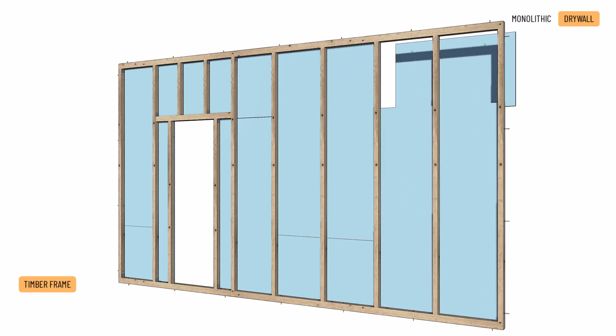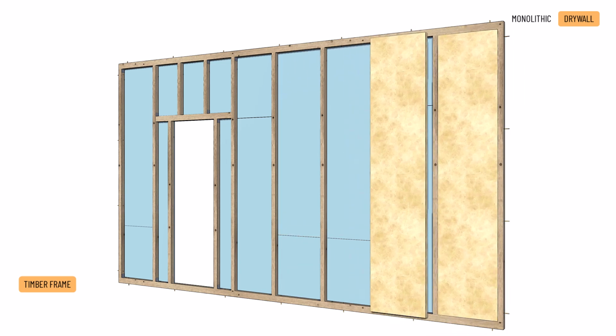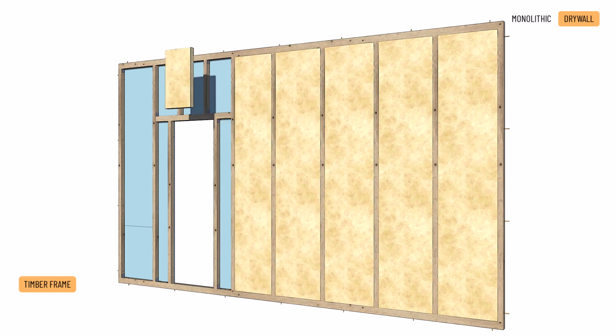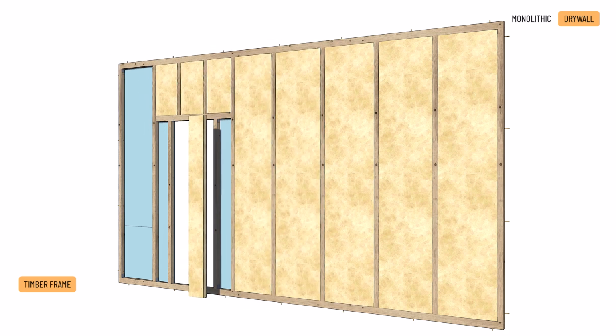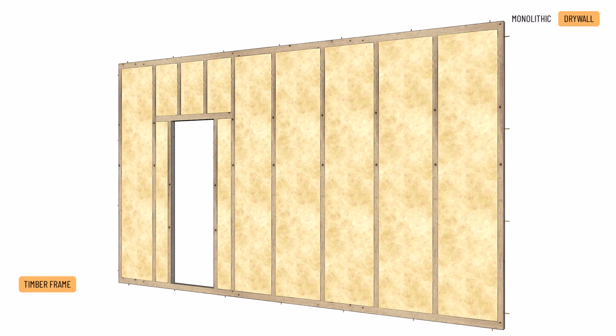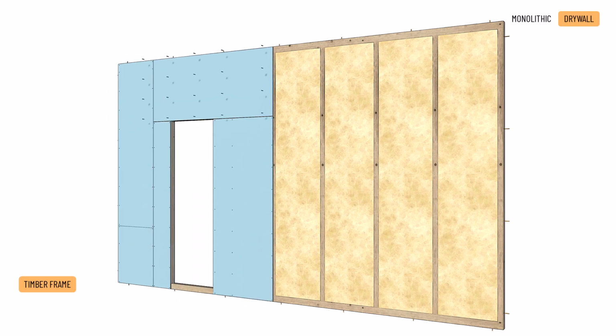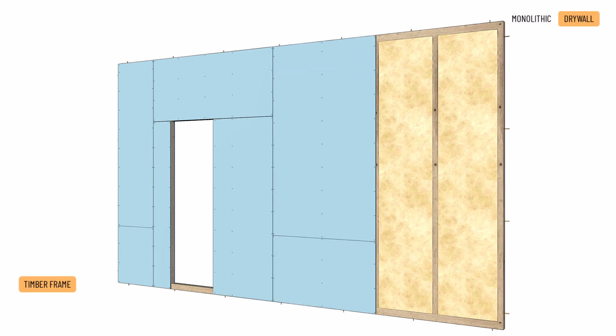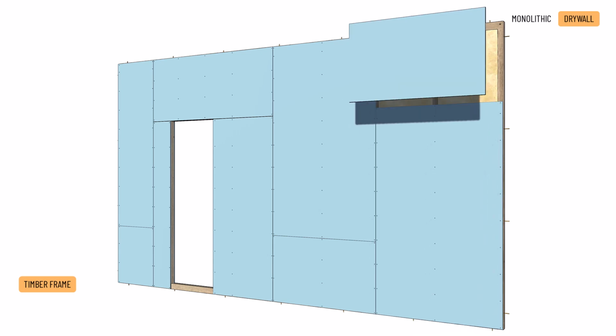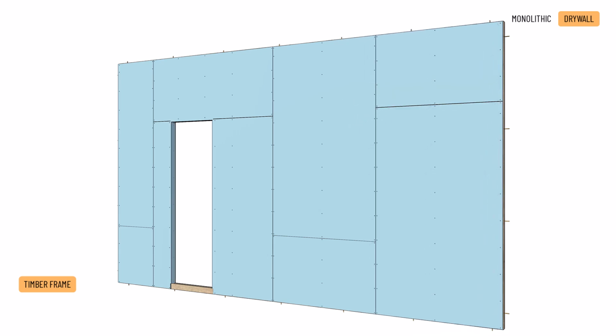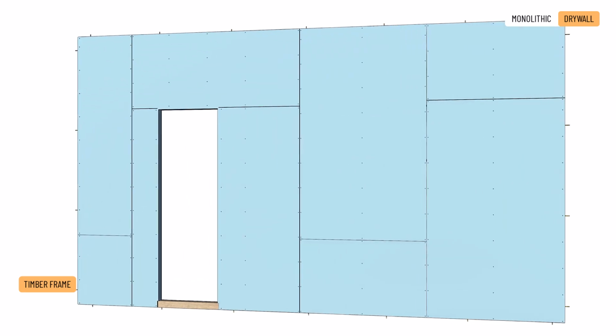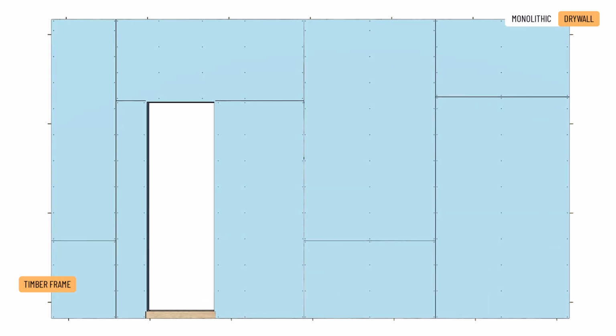Mineral fibre wool, glass wool or rock wool is placed between the studs to provide thermal and acoustic insulation between adjacent rooms. Then, after cutting the individual boards to the required size, screw the gypsum board or plywood onto the stud wall. Putty can be used for the board joints, screw heads and other irregularities to form an even, flat surface to prepare it for painting.